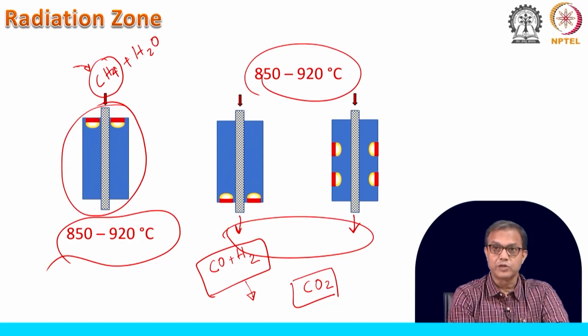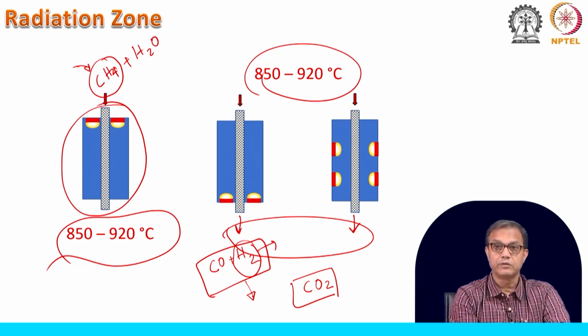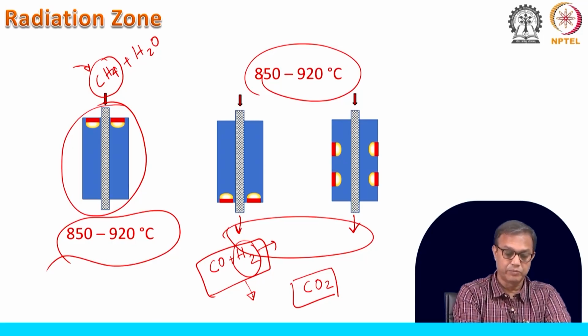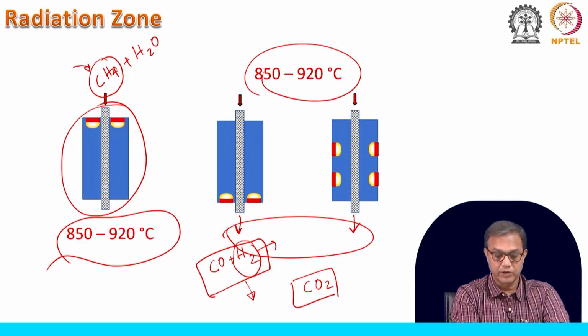So, the high temperature separation of CO2 and finally separating out this H2 needs a certain amount of cooling, and this cooling of these gases will be done by some waste gas recovery, where we cool them down using water, and that water will eventually be useful for generating the steam.